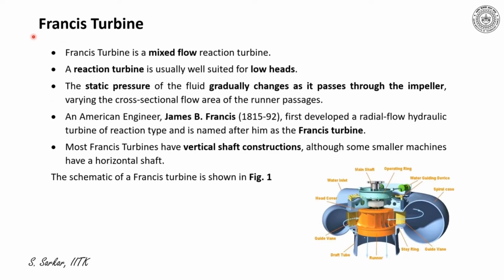I would like to illustrate the features of a Francis turbine. The Francis turbine is a mixed flow reaction turbine. Moreover, a reaction turbine is usually well suited for low head and high flow rates. I have already indicated earlier, but further I would like to add here that the static pressure of the fluid gradually changes as it passes through the impeller, varying the cross-sectional flow area of the runner passage.